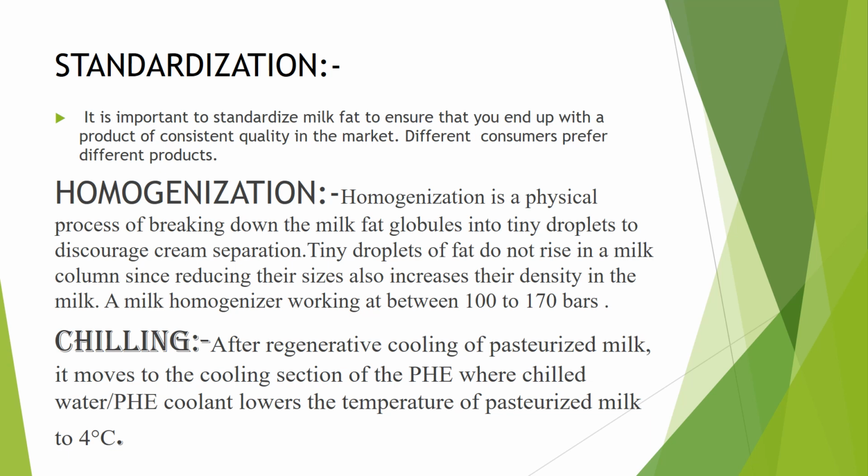The next process involved is chilling. After regenerative cooling of pasteurized milk, the milk is going to be chilled to 4 degrees centigrade. It moves to the cooling section of the PHE, where chilled water or PHE coolant lowers the temperature of pasteurized milk to 4 degrees centigrade.